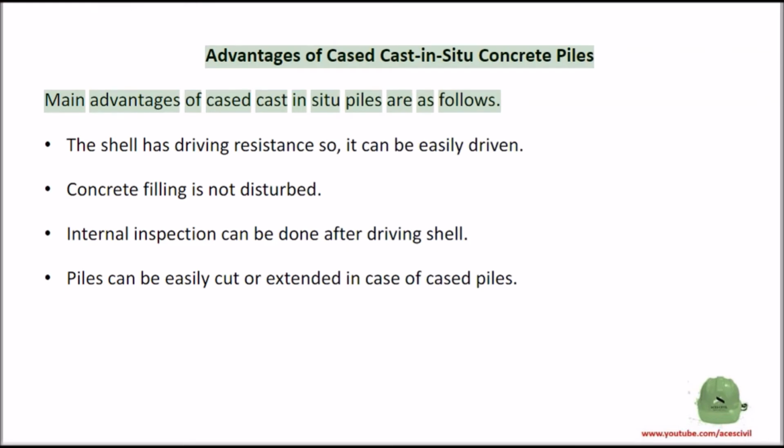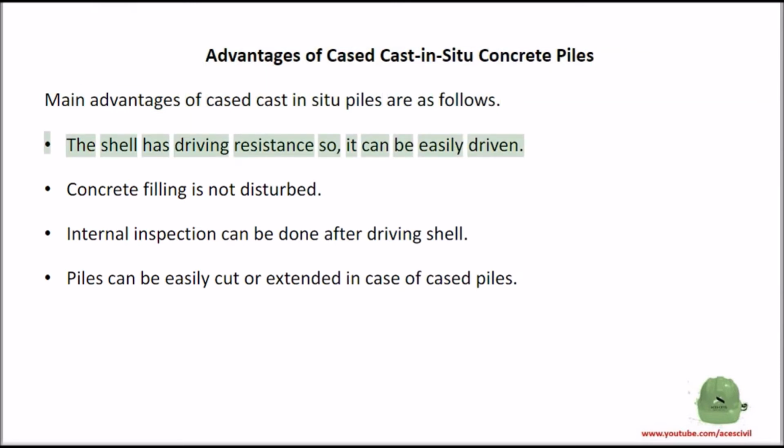Advantages of cased cast in situ concrete piles. The main advantages of cased cast in situ piles are as follows. The shell has driving resistance, so it can be easily driven. Concrete filling is not disturbed. Internal inspection can be done after driving the shell. Piles can be easily cut or extended in the case of cased piles.